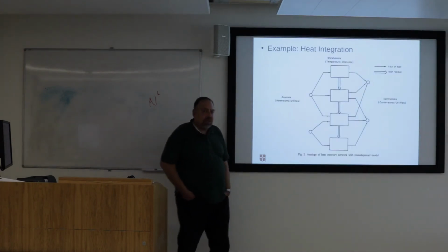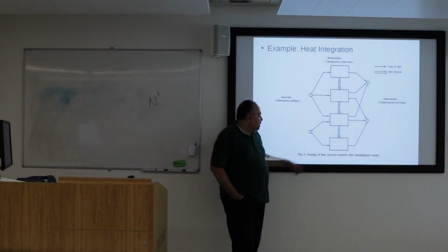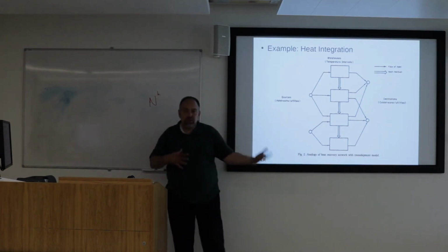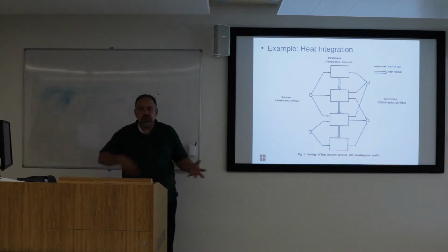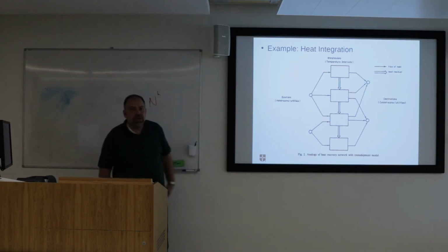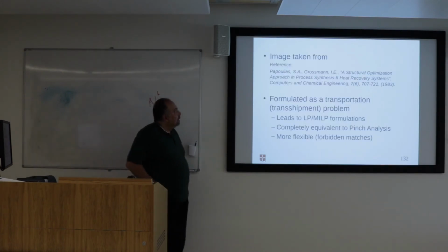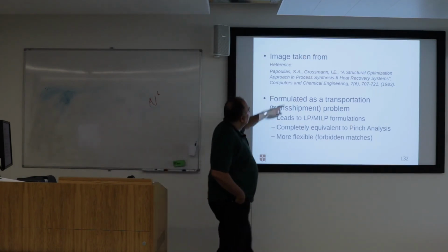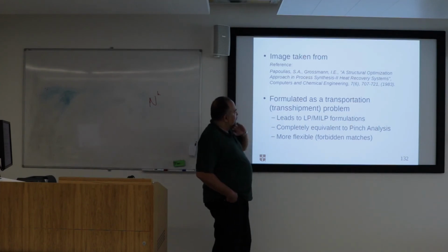Another application is in heat integration, where there is an analogy of a heat recovery network with a transshipment model, where you shift energy from one source to another sink, and those are the temperature intervals from a pinch analysis. And this is some old work that was shown in the 1980s, 1983.